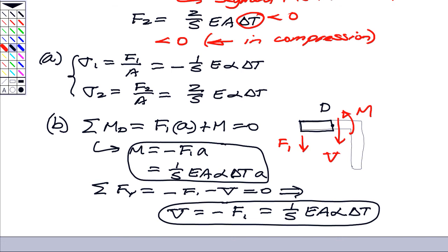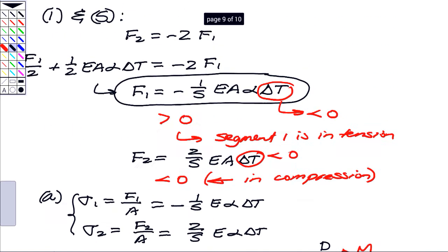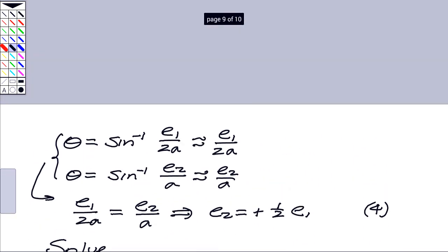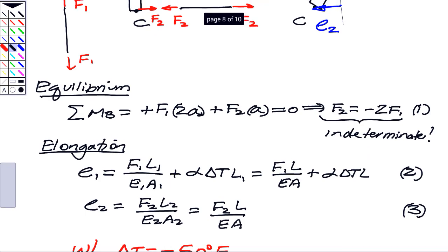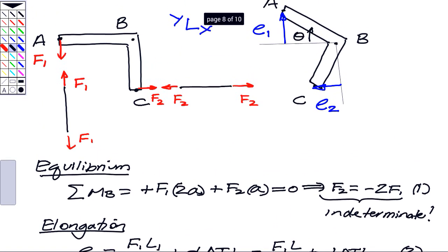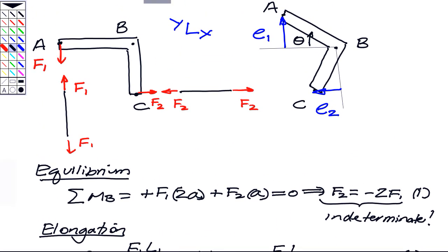So just going back over what we did, we drew the FBD of the L-shaped bracket. And what I did, which is going to be consistent with what we're going to do here all semester, is show both members 1 and 2 as being in tension. I don't know in advance which one is which, or at least I don't care what it is when I draw the FBD.